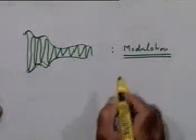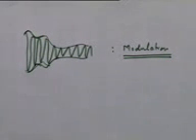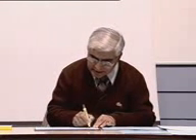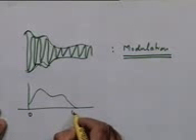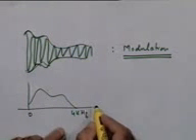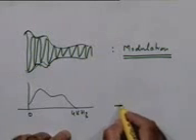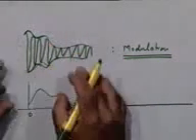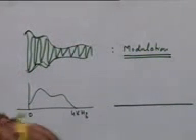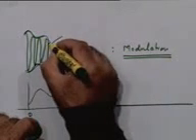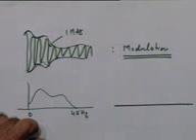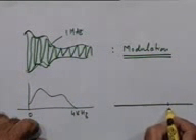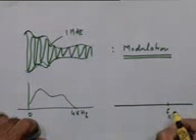Now, that's the reason for using modulation. Modulation helps me to translate the spectrum of the signal, which was earlier lying in the band from, let's say, 0 to 4 kilohertz. Where does the spectrum translate to now? What is the spectral occupancy of this signal? Let's say this carrier I choose as 1 megahertz. It's a carrier frequency of 1 megahertz. So the center frequency of this will be around 1 megahertz.